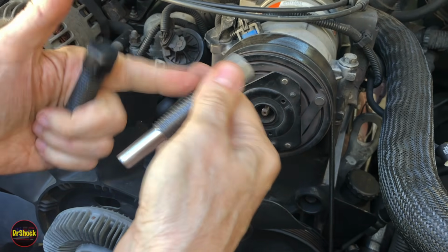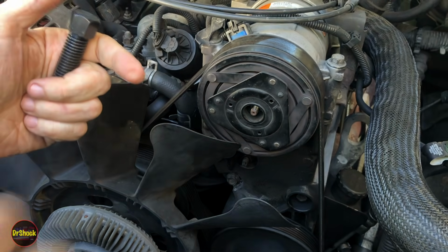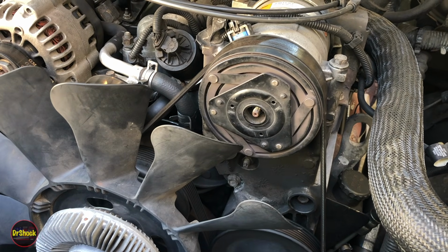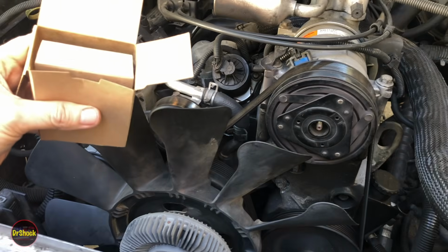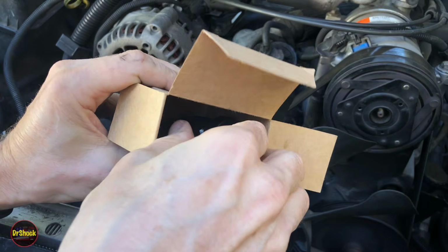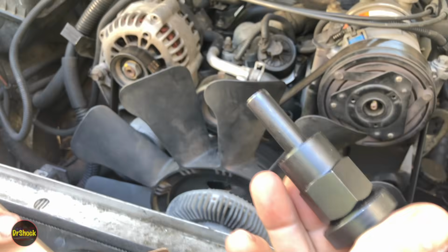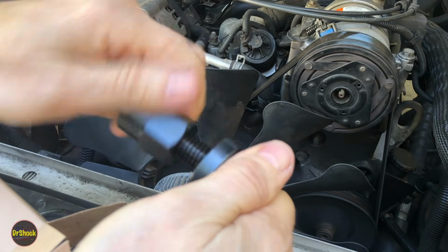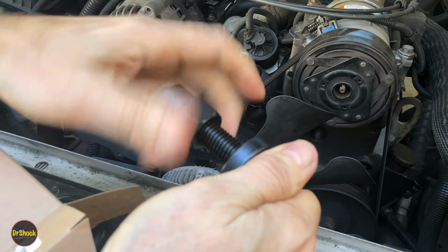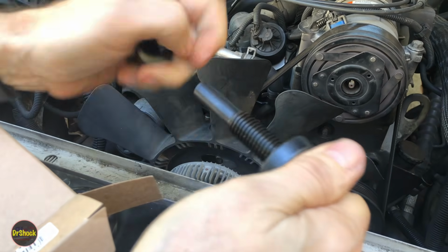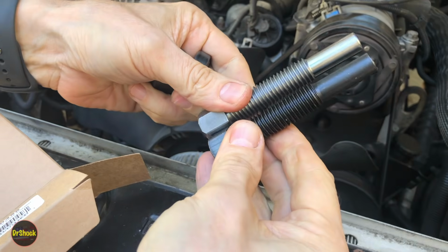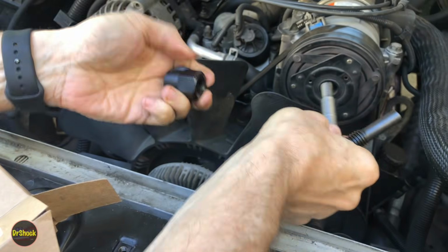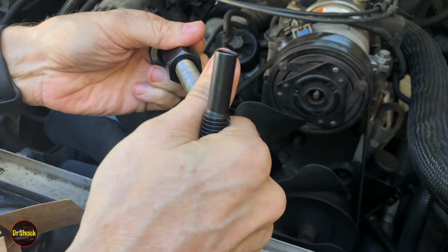So let's go ahead and get our nut and our thrust washer, and let's get the gap closed down on this. All right, with this guy, I'm going to actually use my Master Cool's thrust nut, forcing nut and thrust washer, because it's a little thinner than the other one. And when they cut this, they made these threads just a little longer than I would have liked. So I'd be happier with it going on like this. So I'm going to get this guy going.